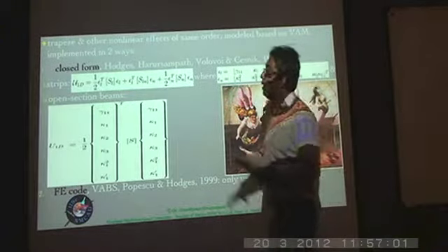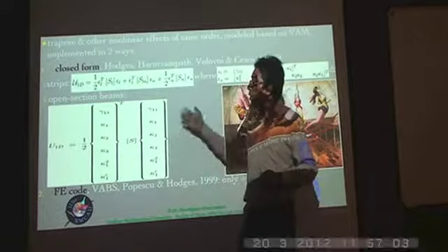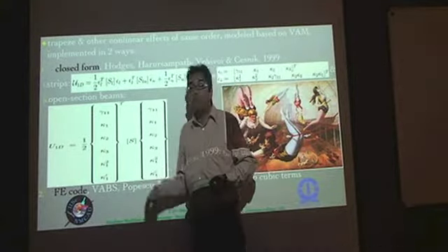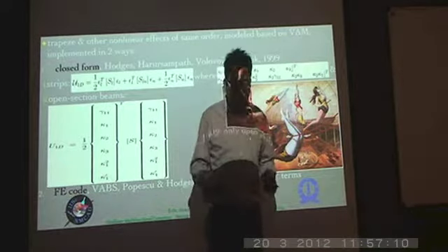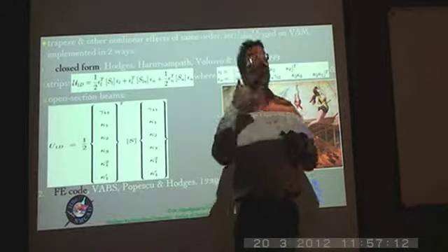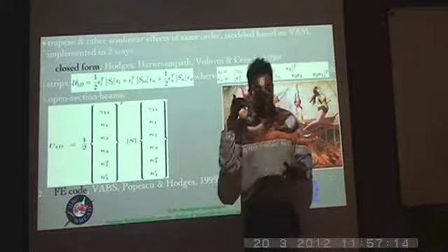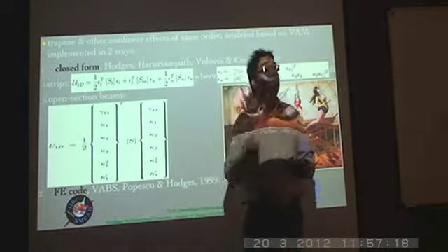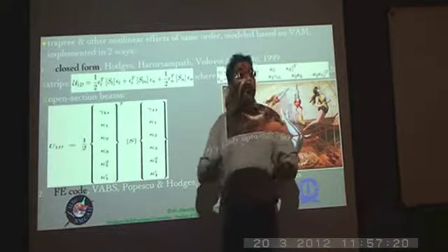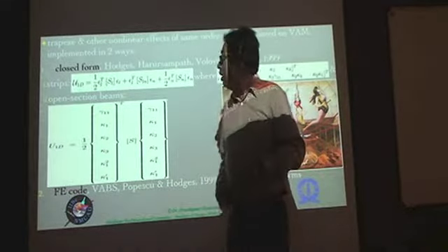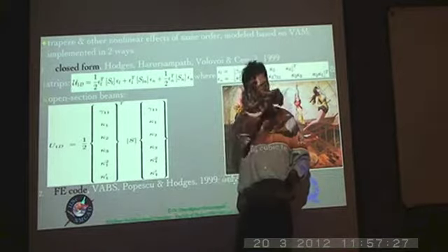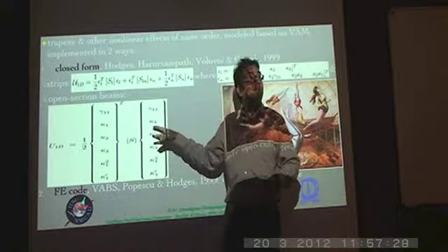Next, for the same thing, closed form analytical solutions can also be obtained and have been obtained for open section beams, which can be thought of as made out of components, each of which is a strip. Like for example, an I section can be thought of as made out of 3 strips, 2 being the flanges and 1 being the web. Similarly, a channel section or a T section, etc. So in all such situations, you will see that the asymptotically correct first order solution basically takes this particular form.